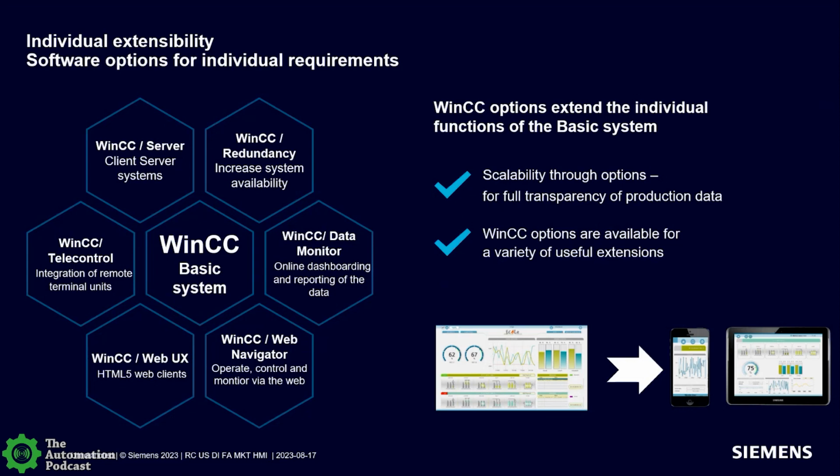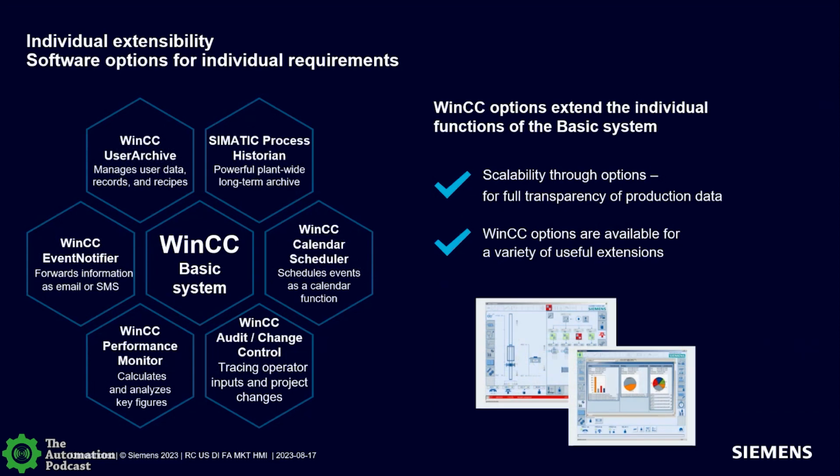And then WinCC telecontrol, that was an extra driver I'd mentioned earlier when you were looking for extra cost. Telecontrol just allows us to connect to a lot more RTU units out there, remote terminals. So if you've got a large wastewater facility, for example, with lots of pump stations on radio communications, that's where telecontrol can help and help build that radio communication to pull the information back out of the RTU units. We continue on this path of added extras.